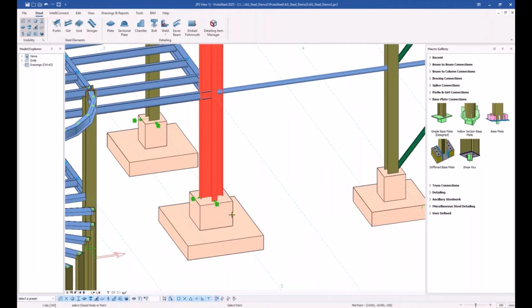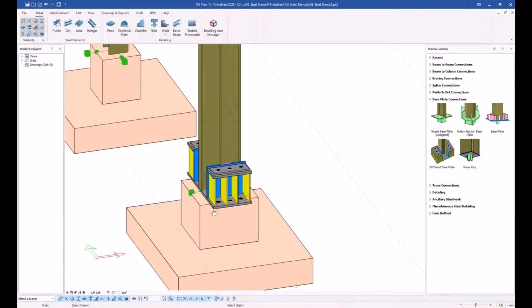like this. Okay, here we go. This is an exposed base plate with the extended anchor bolts. As you know, the column base connections are one of the most critical components of special steel moment frames, because they transfer the demands from the superstructure to the concrete foundation, and this creates an interface between them.